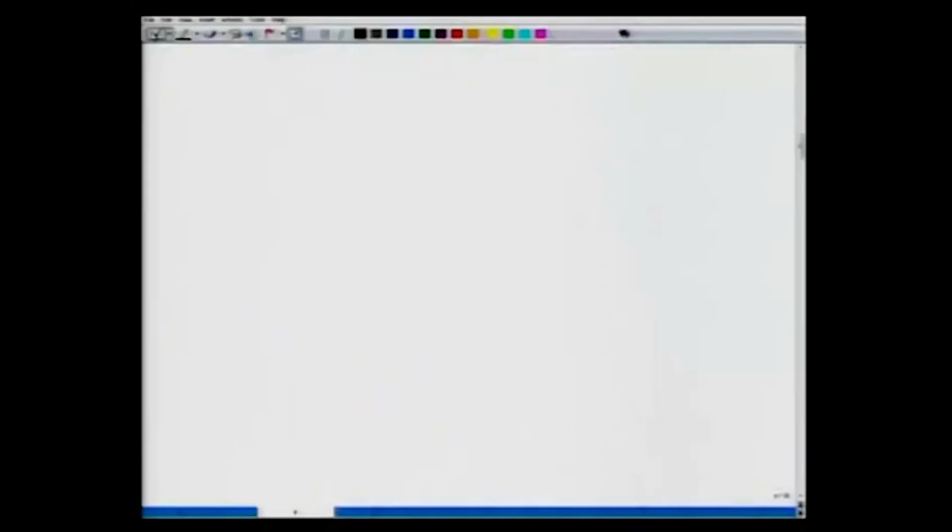There's one more thing which we must address before we end this lecture. We redraw the equilibrium curve. So let's say that we have y versus x, and the shape of the curve is S shape. So let's say it's like this. Now let us mark the coordinates here. So we have y1. This is the mole fraction of the influent gas. So we are looking at levels 1 and 2 here. Gas gets in.